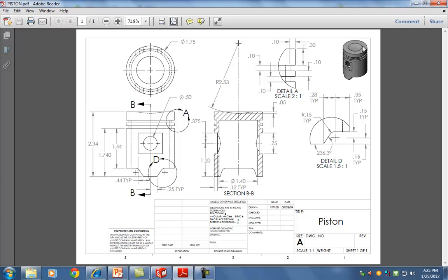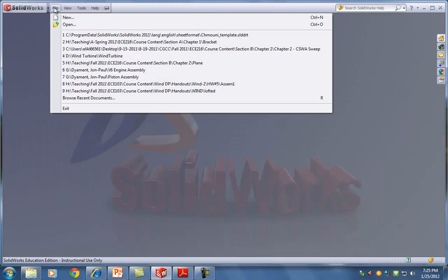Another thing we have to notice is there's that divot on the top. You see that groove? That is created from this arc. So how can we create that, and what can we do about it? Let's go ahead and start from the front plane.